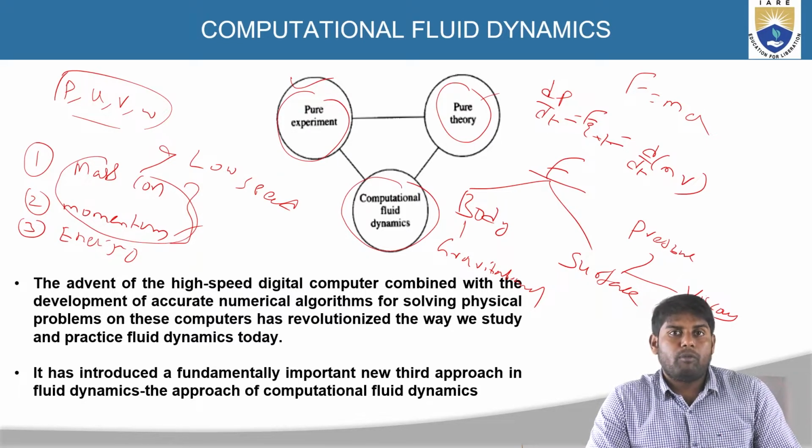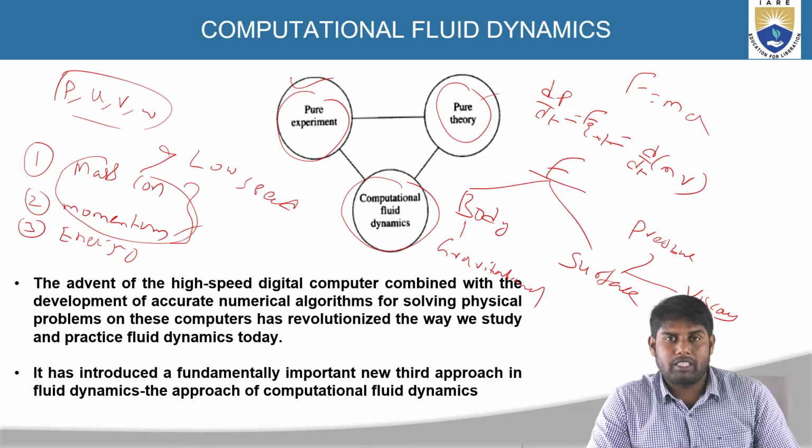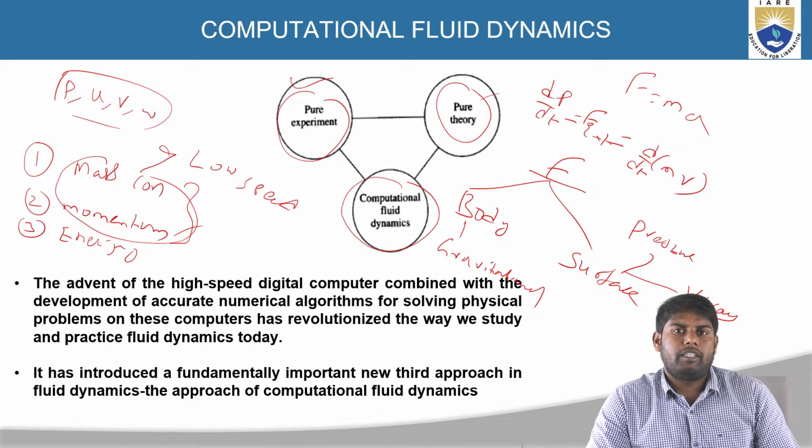So the momentum equation will give us the information regarding the pressure gradient and the shear gradient, and then after that you will know the local acceleration, convective acceleration, and the body force term. So for a low speed flow, the continuity equation and the momentum equation alone would be sufficient to solve the flow properties and get the values.